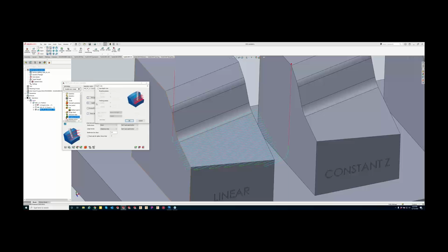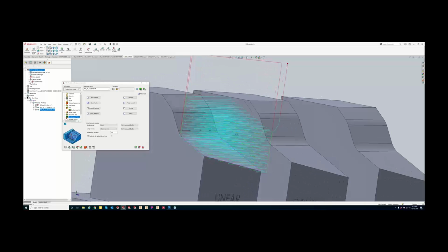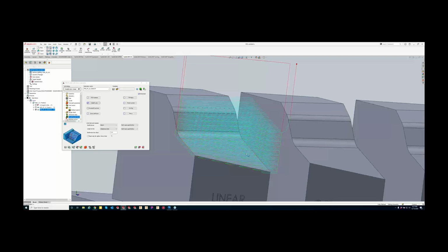We would use our depth cuts. And let's just do 10 at a spacing of 100 thou. Basically what it's going to do is take my tool path and offset it up by 100 thou. So the exact same tool path, I just offset it up by 100 thou. So each pass is doing 100 thou there.